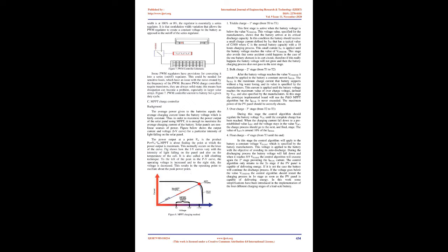In this method, the charging voltage is kept constant throughout the charging process. The charging current is high in the beginning when the battery is in the discharged condition. The current value gradually drops off as the battery picks up charge, resulting in an increase in back EMF.